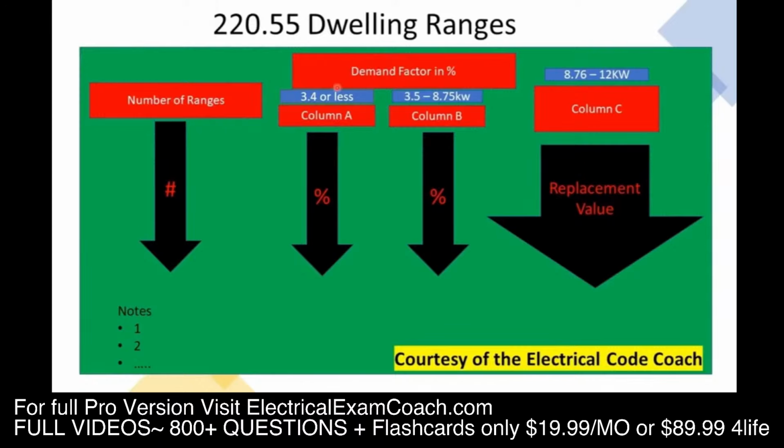Then we're going to notice that there's 3 different columns. They're really in two different groups. Column A and column B are grouped together under the demand factor in percentage column. And the reason that's so important for us to watch out is because column A and column B are multipliers. They're actual demand factors. But column C is a replacement value, and you'll understand more of what that means as we get farther through this video.